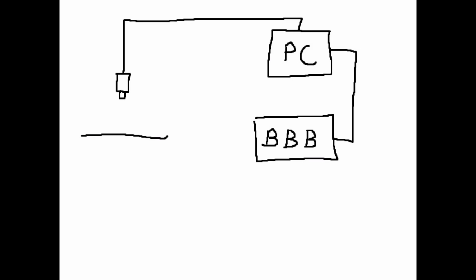Inside the Walnut client software, there are subroutines called action modules and behavior modules. Action modules interpret the incoming command and pass the data into the appropriate behavior modules, which then interpret the data, red and green square locations for example, and generate simple things like the speed and direction values that will ultimately control the motors. The important thing is that the behavior modules are not stateless. They are aware of what they have previously output. This makes it possible for them to do things like adjust their output, slow down or speed up, based on how fast they are approaching the desired target. In other words, PID control is possible.